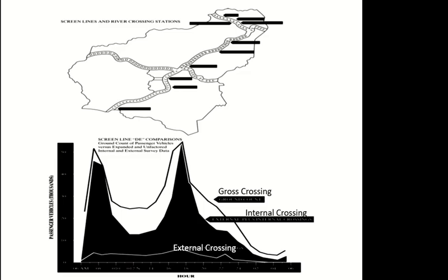Now in screen line count, the procedure is the same as we discussed for origin destination. You take the count, you make the simple small 2 by 2 OD matrix, you take the field count and you adjust and so on, so it will be easier. But in an OD matrix we usually cover the entire city. So the trips which are not from my zones are very few, negligible, because I already covered the entire city. But in a screen line count, I'm only covering two districts or two areas. So there will be a lot of trips which are not from these two areas, but are still crossing. Let's say I'm doing it between Manama and Muharraq, and there could be a guy who is coming from Hidd, and he is crossing Muharraq and will go somewhere else. So this guy is just crossing. He may show up in my count, but he is not from these two areas, Manama and Muharraq.